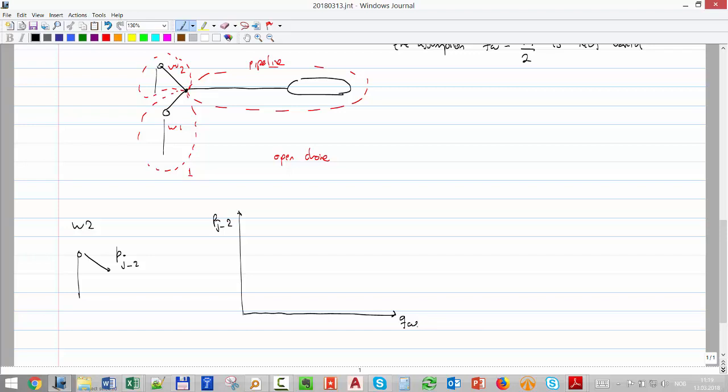So for that curve, I have to go from reservoir pressure 2, to bottom hole pressure 2. There I go up to wellhead pressure 2, and then I go to junction 2. I may potentially have to use an IPR, a tubing equation, and a flow line equation. But no matter how you calculate, it looks like that. That's how the available pressure curve looks.